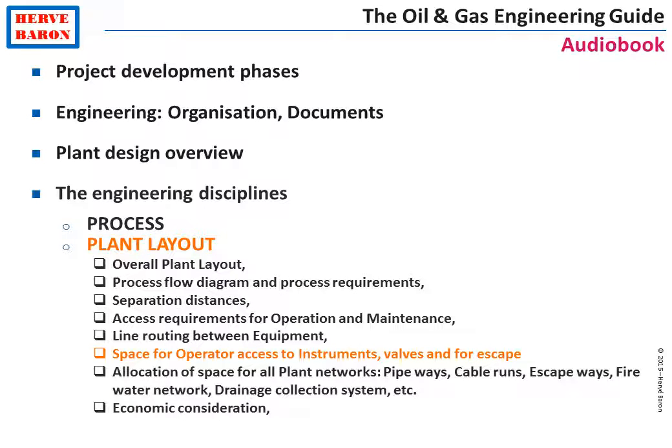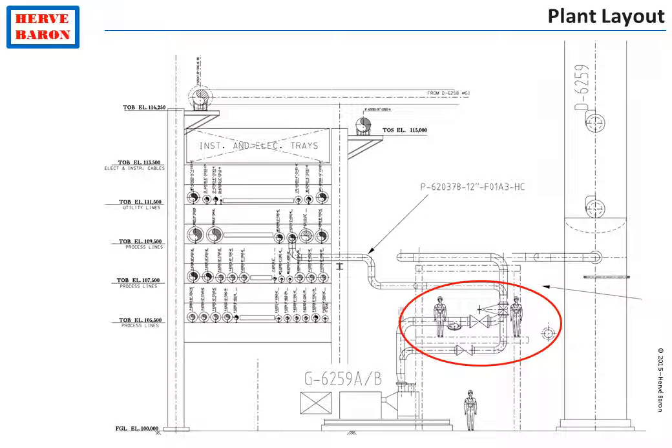Space must be provided for operators to access instruments and valves. For instance, one has to take into account that the operator needs to access the suction and discharge valves on the lines feeding this pump, as well as the strainer and any instruments present on these lines.